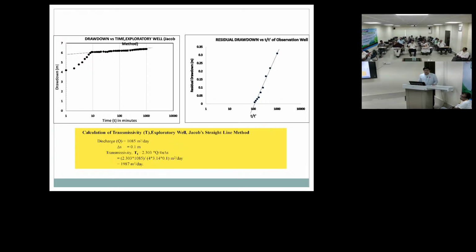It depends on the aquifer property. If it is very well saturated, like in the alluvial areas, it will take around half an hour, but in a hard rock area, it will take around 5-6 hours to recover. So that also matters, because the maximum hours of pumping you need to define depends on the recovery also. Without recovery, if you keep pumping a well, the water has not fully recovered, and definitely a breakdown of the motor will be there. People will say we haven't got water. So ultimately, only pumping is not effective. We have to take recovery into consideration.